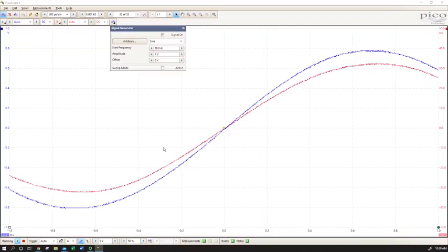We can compare that we had F resonance with the same value of capacitor at 950 hertz with our relay inductor. Now with that same capacitor, F resonance is at about a third. So obviously that means we're going to have a corresponding difference in inductance. So if I use 363 as F resonance and I use my capacitance of 47 nanofarads, use my expression for resonance, I end up getting around 4.1 to 4.2 henries for my inductance corresponding to this primary side of the transformer.